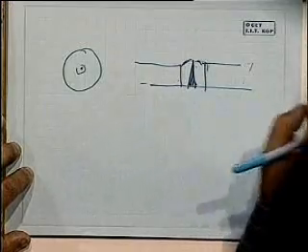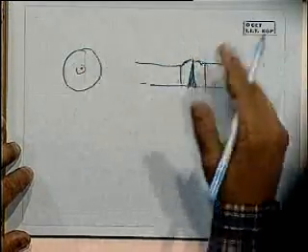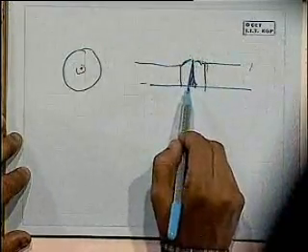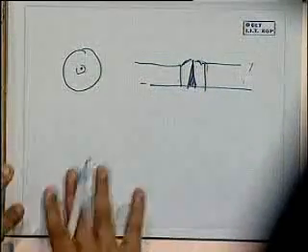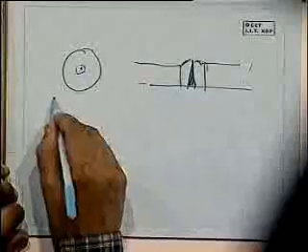I'm not making them one at a time. We put a mask and suitably etch it and so on, and we get these tips. So very rapidly I can design, and I can do this over fairly large areas. Maybe that is a limitation, because right now we'll have to make it in a substrate, and if we're going to use silicon, obviously I don't have silicon substrates that are that big, but obviously I don't have to do this in silicon. I can do this in other kinds of substrates that are coated and make these tips. So this is one interesting application of this phenomenon of field emission.